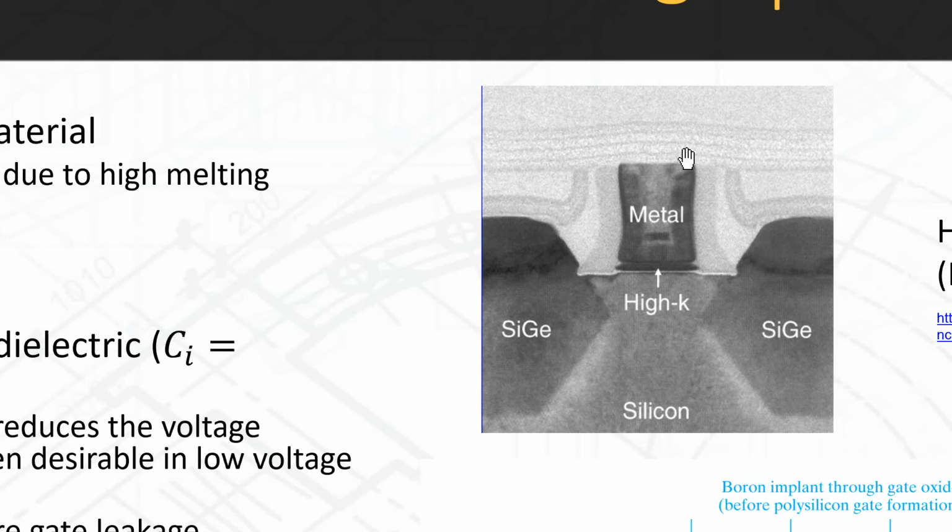You have your transistors, but you also need to connect your transistors to other transistors, right? So they have different metallization layers. After they make all the transistors on the substrate, the next step is to create metal layers where you draw a metal trace between the source of this transistor with the drain of this transistor with the gate of another transistor. And that's all encapsulated in that little black package, what we see as the processor. Oh yeah, so that might be those ghosted lines up there? Yeah, that's what I'm guessing.